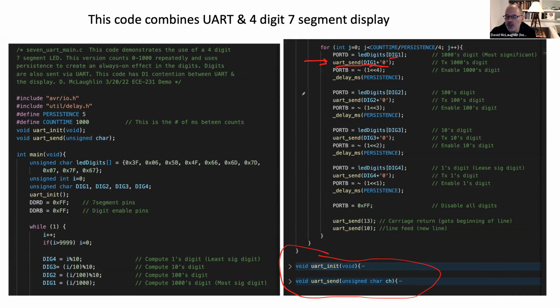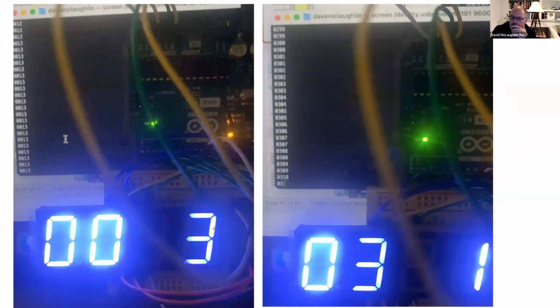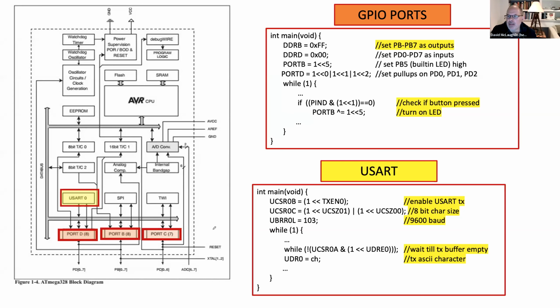You take advantage of the retinal persistence. You can figure out how fast you want to do it. You can also send the data to the monitor via the UART. Okay, so there's quite a bit here, but as I've emphasized several times, the code in itself is not all that complicated compared to coding from data structures or even for some of the other things that you did in your first programming class. We're just working with a while loop, but the key is you have to know how to twiddle all those bits. Okay, all right. That's all I wanted to say about that.